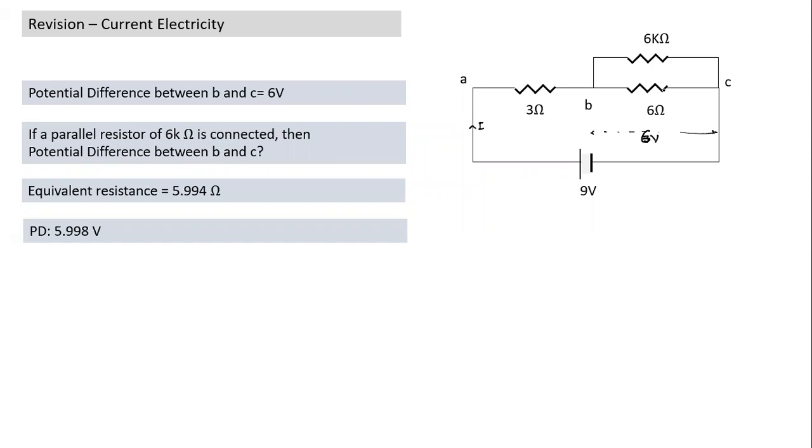And so what has happened when I connected this? See what has happened. If I have connected a very large resistance, there's a very small change in the equivalent resistance here. Resistance has decreased here. If the equivalent resistance for the circuit has decreased, it means current will increase. The circuit has changed, so current has gone up here. More current will flow now than what was flowing earlier. As current increases, this part here, where earlier the potential drop was 3 volts, the potential drop across AB, VAB, will increase.